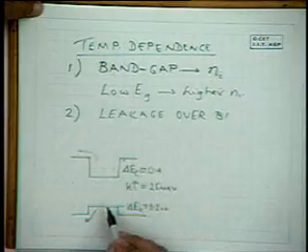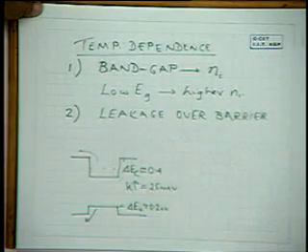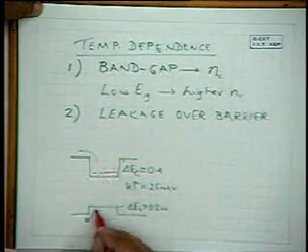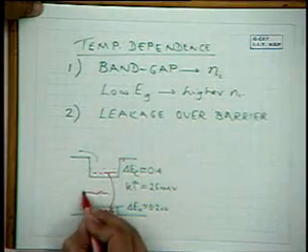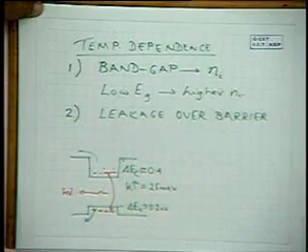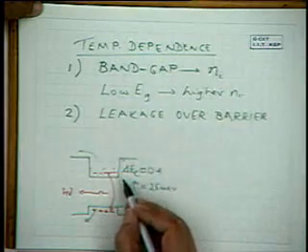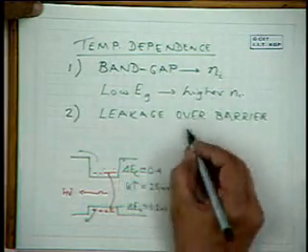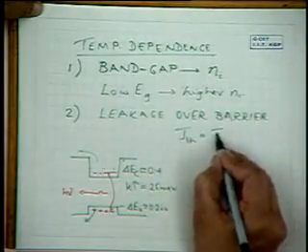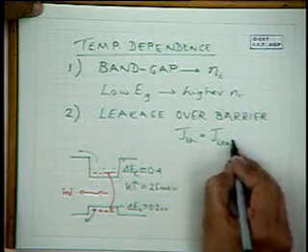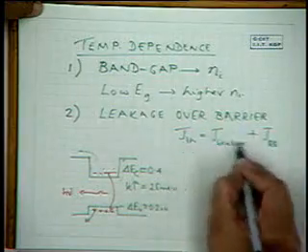So this leakage current will reduce the radiative recombination. Instead of the carriers, electrons and holes recombining directly, giving out light, confinement will be poorer, and so the threshold current will increase. In fact, you know, the expression for JTH, in practice there will be a J leakage plus the J radiative recombination. So this will increase.